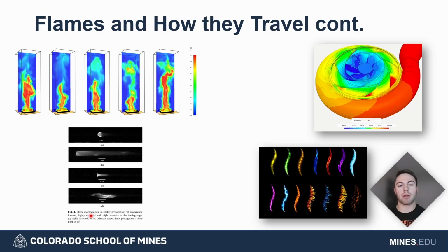If you are trying to model a more complicated flame, like a turbulent flame, you're going to require something called CFD, or computational fluid dynamics, and that takes a lot of computing power and gives you fairly accurate results for very complicated systems. Though, again, the same applies for both the laminar model and the CFD modeling: you are going to have a model that is only as good as the assumptions that you put into that